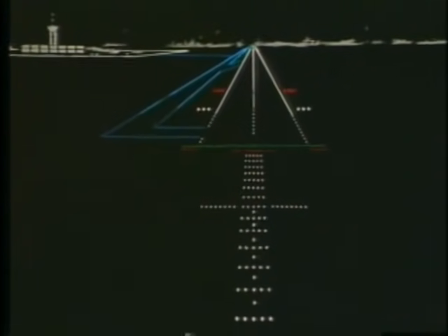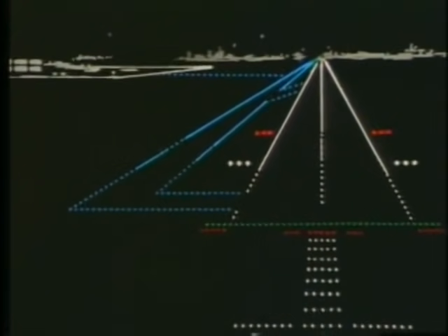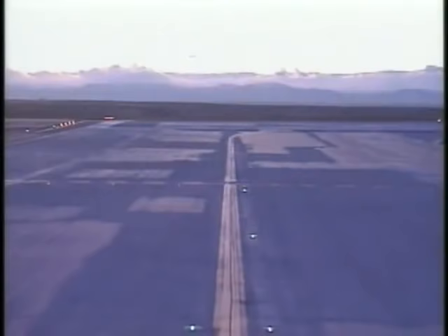The taxiway lights provide direction while on taxiways, entering and exiting runways, and taxiing to other surface locations on the airport. The amount of lighting varies greatly depending on the size of the airport. Taxiways are outlined in blue lights or blue reflectors. Additional taxiway lighting may be used during periods of low visibility. For example, green taxiway centerline lights may be available at some airports.